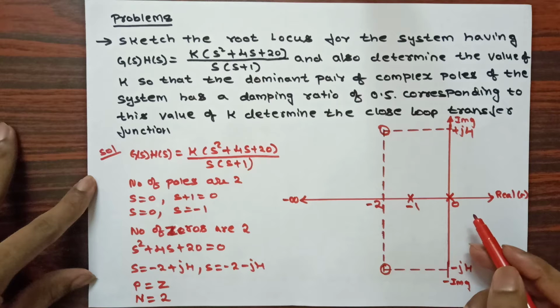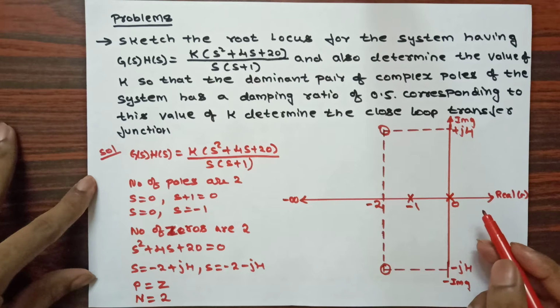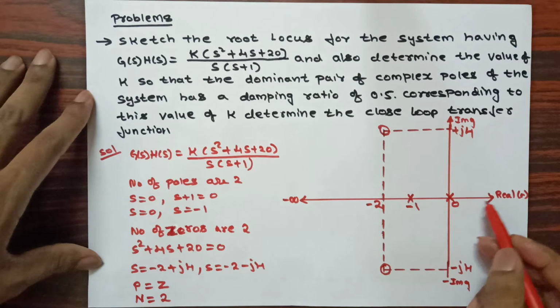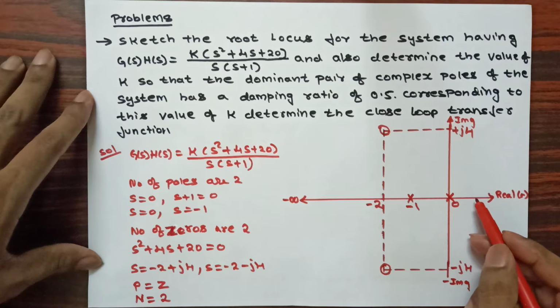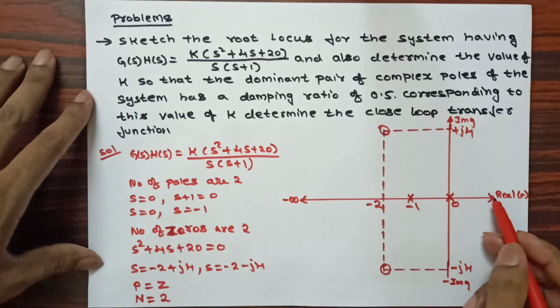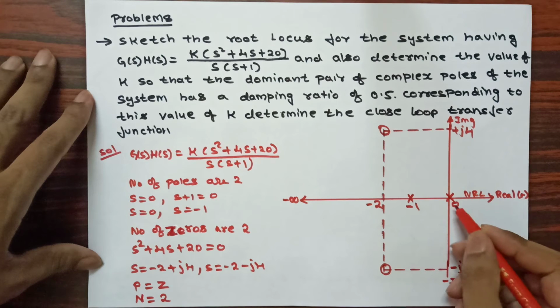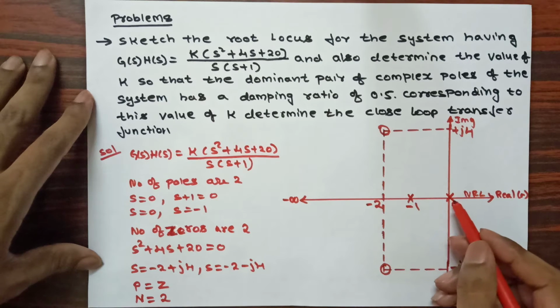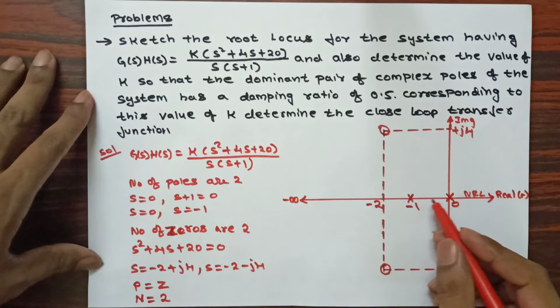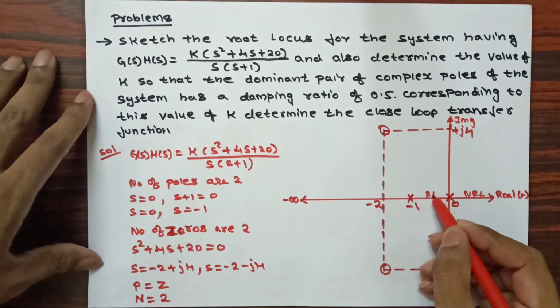Next we are going to identify the root locus path and no root locus path. From this point to this point, I am not having any poles or zeros, that is the count is 0. 0 is an even count. For this portion, I am going to consider no root locus path. And at this point I am getting one pole, that is count is 1. 1 is an odd count. From this point to the next point, I am going to consider the root locus path.